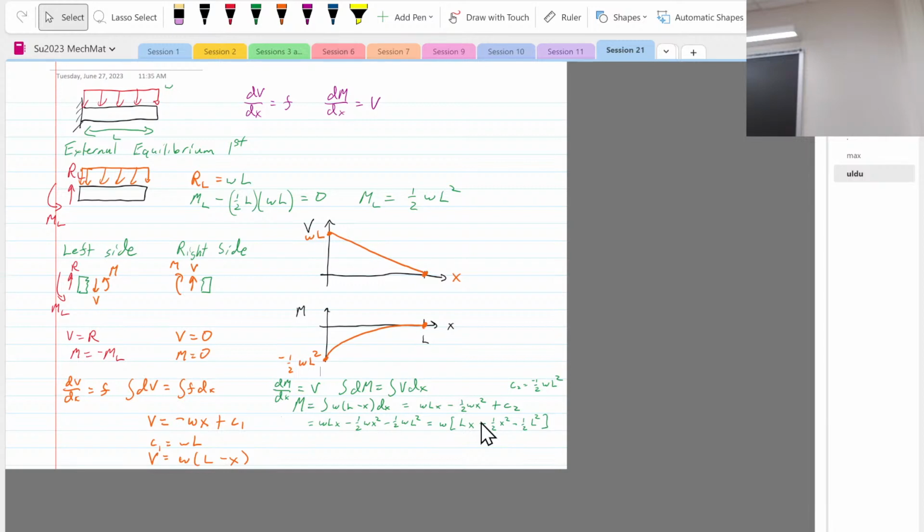But don't you have to find the two stresses? You only need one stress to start, because if this is zero, it's just stress over 2 squared plus the shear squared. You have that normal stress. Not the shear, just this one. And this stress is divided by 2, squared.